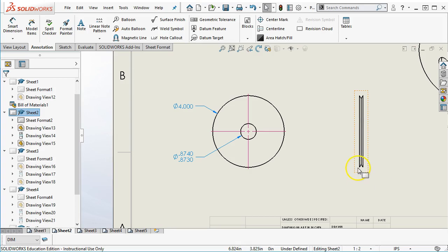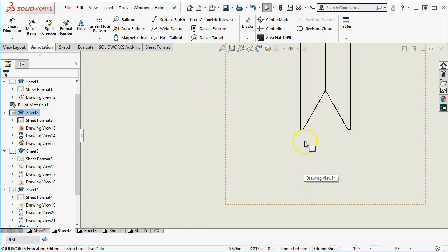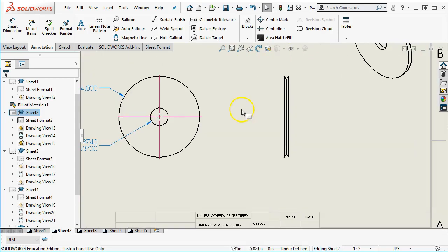All right, I would not pick the two little cylindrical arcs or the flats down here that represent that arc, because I'm not going to set that on end on my surface plate to measure anything and get any kind of accurate measurement out of it. And those are pretty much the three choices: the top, the bottom, or the diameter. And the V, nah, that's okay. Don't even want to talk about the V group.